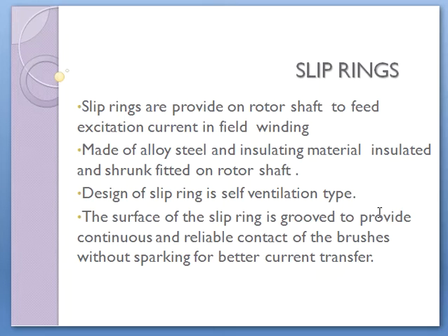They are made of alloy steel and insulating material, insulated and shrunk fit on the rotor shaft. The surface of the slip ring is grooved to provide continuous and reliable contact of the brushes without sparking for better current transfer.